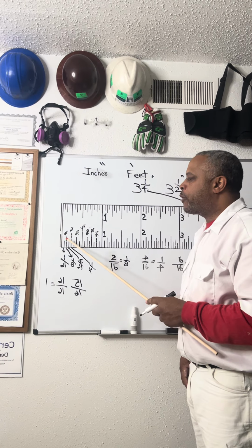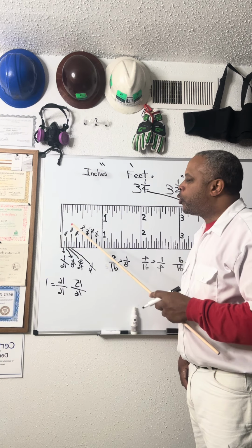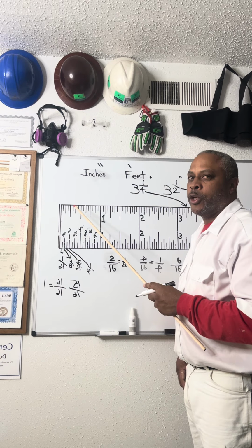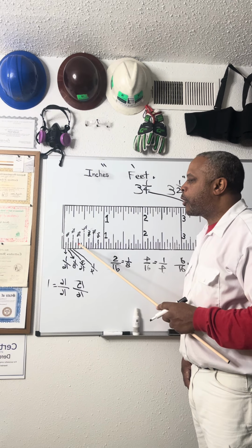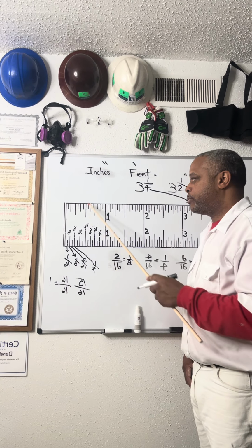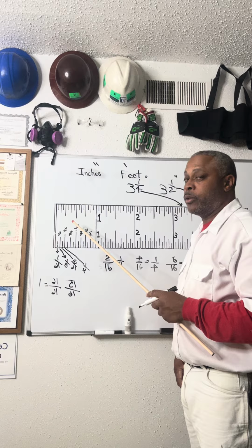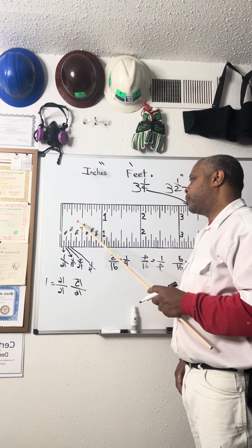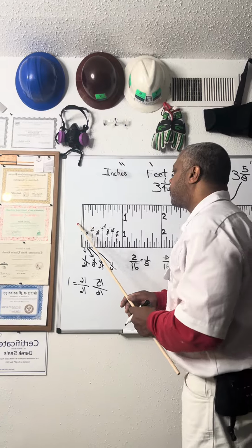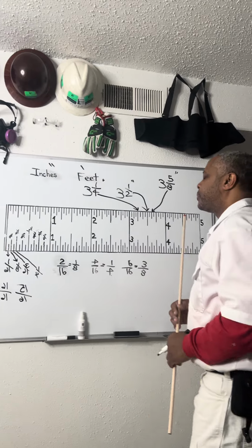Whatever you have at the bottom here, you can read that same number up at the top of your ruler. Your ruler is transferred on both sides of the blade. This is the blade of your measuring tape or your measuring ruler, okay? This is the hook. Everything you're hooking off of here, all right?